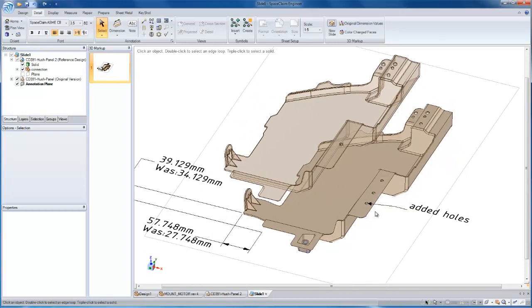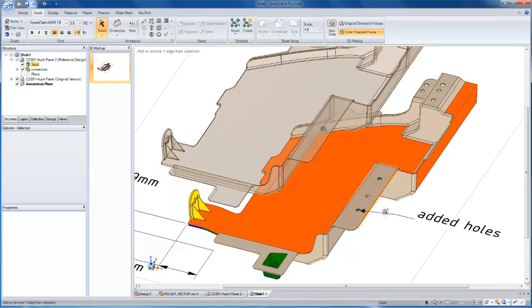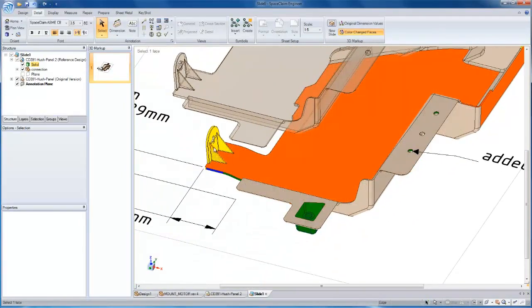And so we give you a tool that just makes it painfully obvious, all the changes you've made. Every modification shows up in color. You see all the green faces are new, and you can see on the doghouse over here. And yellow just means there's a location change. And there's an edge change on any blue faces. So someone could clearly go in and see everything that's been modified.